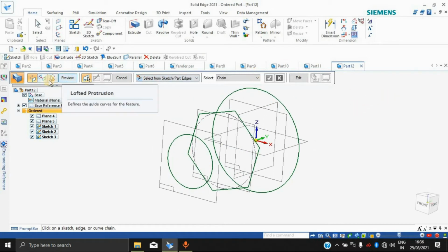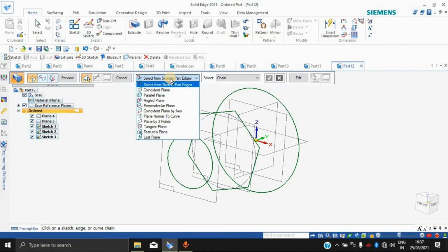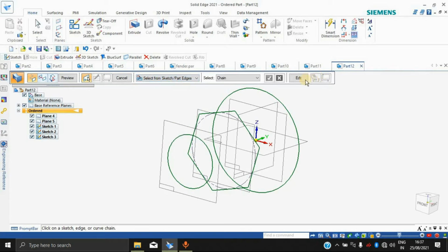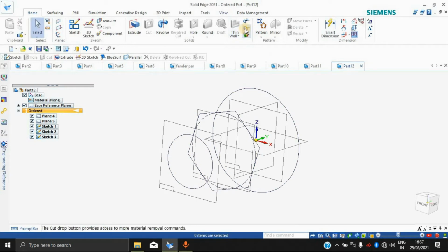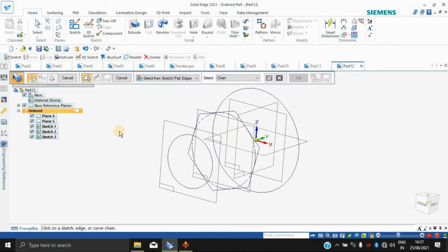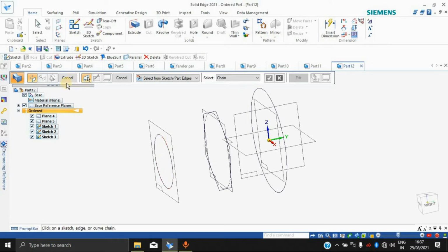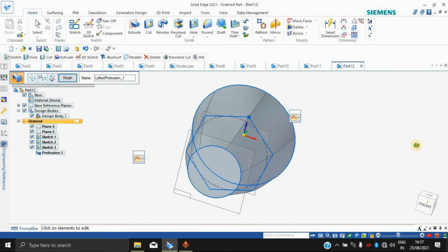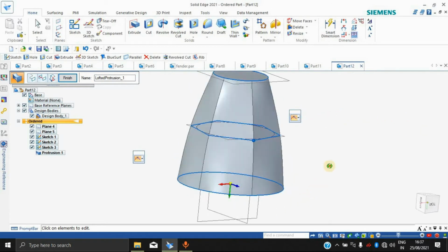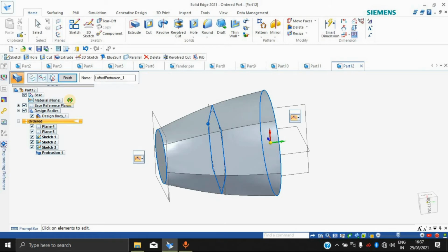So what we'll do is, we'll escape this once again and click on loft. Now, firstly it's asking me for a cross section. I'll give this as a cross section. See, now it has formed a circle and a hexagon in between. So this was basically the loft command.